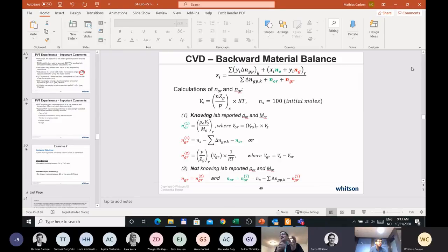You know, you basically have the separator gas composition, the separator oil composition, and it's this recombination ratio that's really the only uncertainty, and there's a limited amount of error coming there in the lab. So there you can get 4, quite wide-ranging compositions with very minimal uncertainty in the compositional data, and 4 pieces of really good data, CCE with the relative oil volume for each. That kind of data would be second on my list, because I know we're never going to go there. It's hard to sell that to the industry.